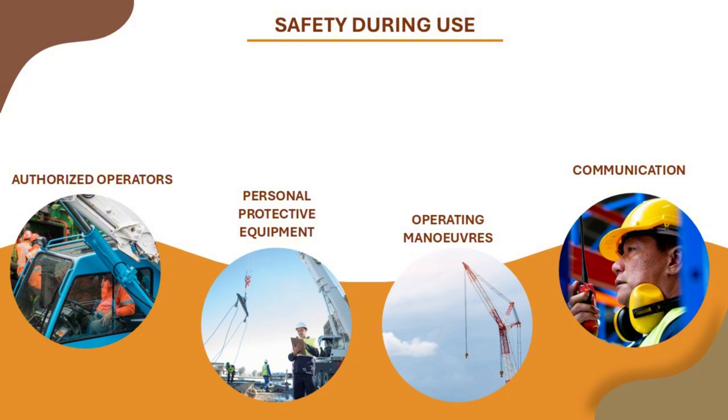Operating maneuvers. Lift loads gradually, avoiding sudden movements or oscillations. Always keep the suspended load within the crane's maneuvering area. Never leave the suspended load unattended.